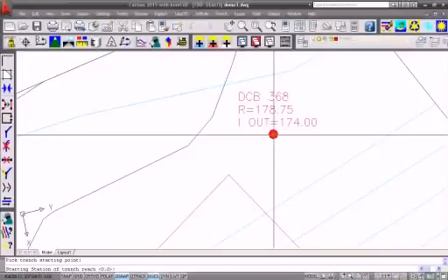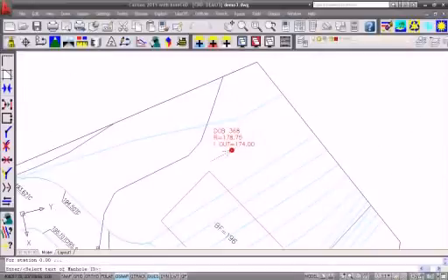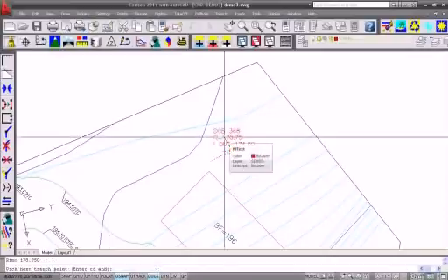Starting station 0, and down here in the bottom, it's going to be the same prompting as you're used to if you're entering in a polyline. So select text of the manhole ID. The invert in, this is my first one, so it's going to be the same as my invert out. And then the rim elevation. Okay? And now it says pick the next point.